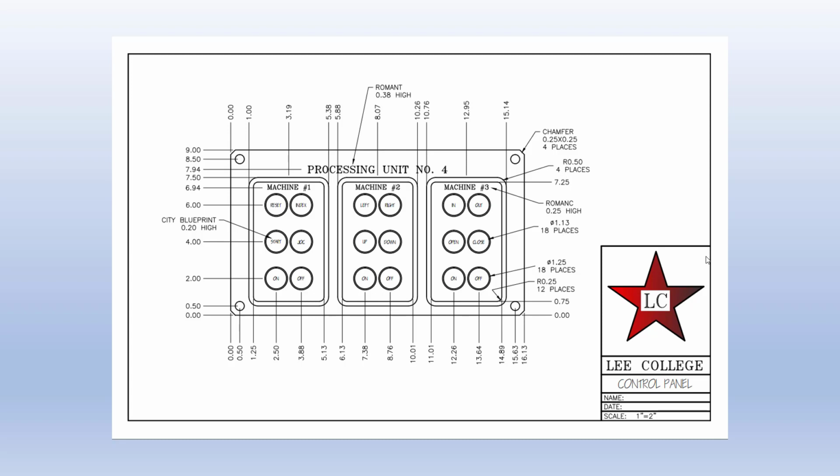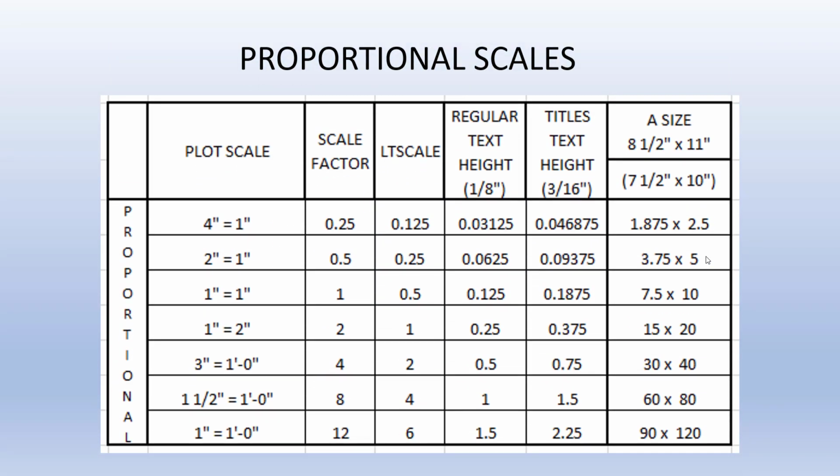It will be your job to decide or figure out what scale you will be using when creating your drawing. The size of the object and the number and type of views that you will need to best present your drawing will guide your decision, as well as other factors related to your drafting discipline. Before we show the process of calculating a scale factor for a drawing, let's take a look at some tables with some commonly used standard plot scales. We will also look at the dimensions of an A-size drawing and border.